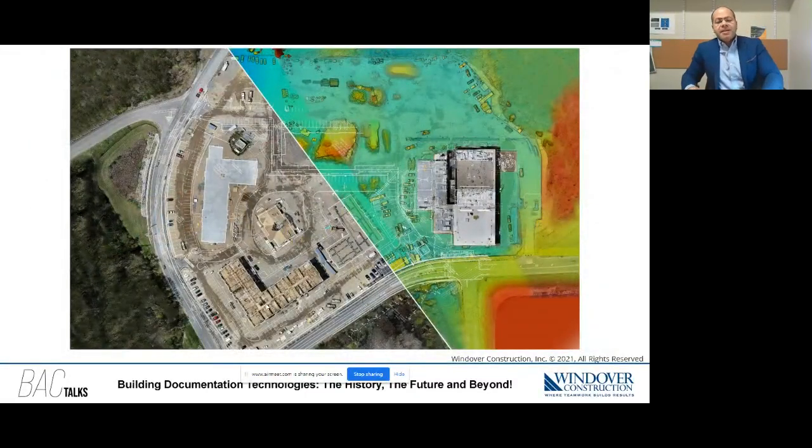This is a 13-acre site in Gloucester, Massachusetts, during the COVID surge back in April. We did regular QA/QC overlays between drone mapping with ground control points and laser scanning, so we can keep track of construction progress, making sure our super, for example, has data. It's more than an eye in the sky. It can capture data for stockpile analysis, with which the superintendent can really calculate how much dirt is coming in and out of the site.